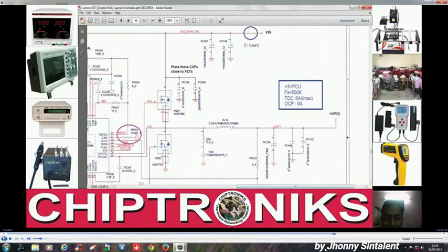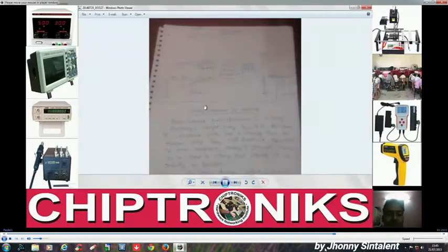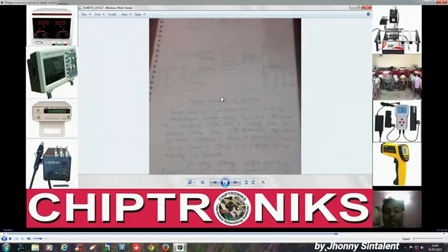So we need to slow down this V error. So that's why an external capacitor is connected. You must have observed some previous voltage regulator circuits where an external electrolytic capacitor is connected, but it is costly to connect an external electrolytic capacitor because the assembling cost would also increase. So nowadays this type of voltage regulators are coming where there is an internal soft start, right? Internal soft start.